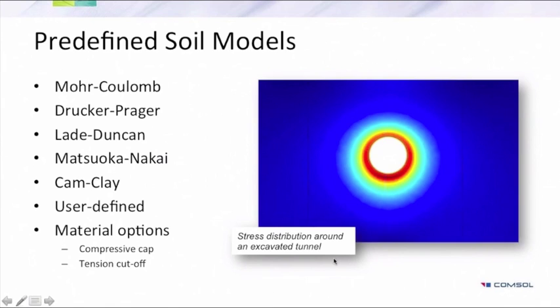The example shows what happens when you excavate a tunnel. The soil will undergo deformation under its own weight, and then if you remove the ground and create a hole, and you put some kind of top pressure, there will be plasticity developing around the hole.